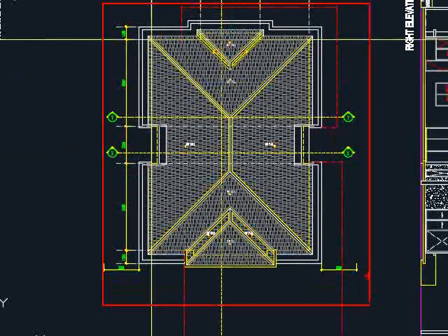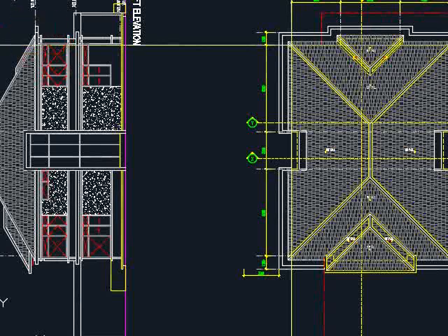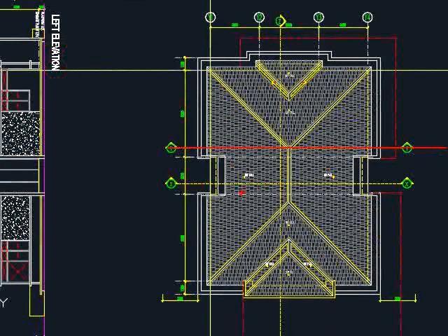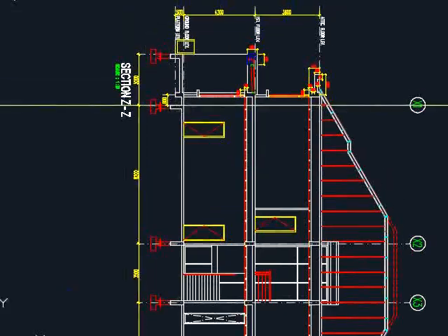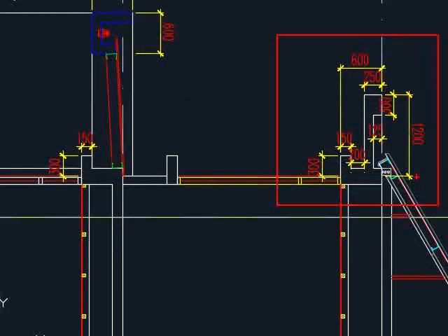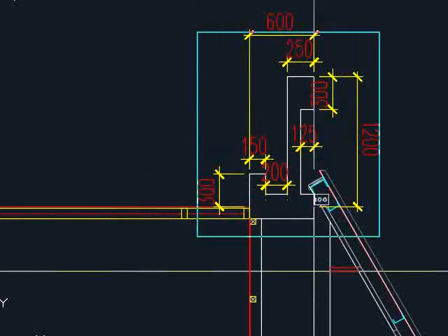And for the roof level, now the entire perimeter of the buildings are with the gutter. You can observe the gutter here to check their locations. Is it in line with your plan? And if you wish to know how the gutter looks like, you can look at the cut sections. Let's say now we are looking for the cut section here. This will be the dimensions of the gutter. It is clearly indicated that this is the attic floor level, and your gutter should look something like this.